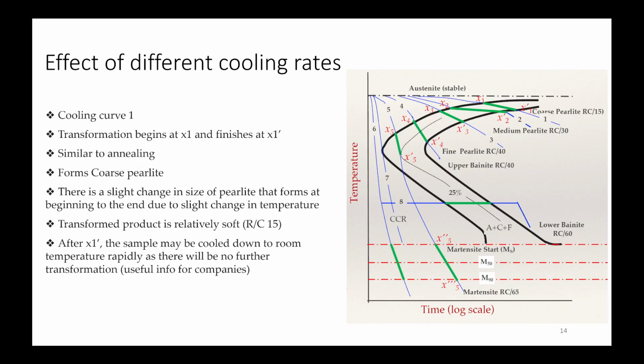So solid solution is more likely to show an isomorphous type of system. If you have already formed Fe3C type of compounds, or Cu3Ni, or these types of intermetallics, then it is less likely to be a complete solid solution up to 100% of another element. So there should be the least difference between the electronegativity.